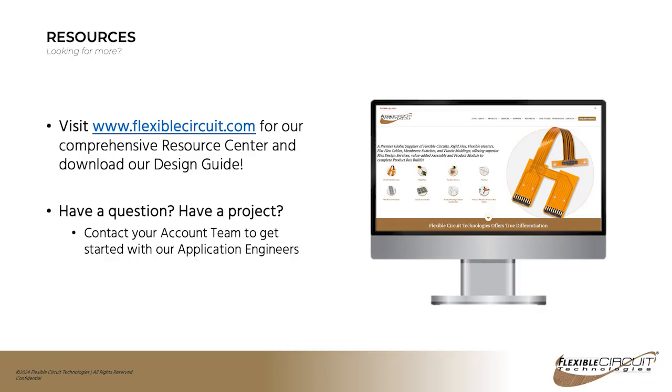Is there any consideration in using fine pitch or ultra fine pitch components on flex circuits? There wouldn't be any additional concerns other than just the fact that if your circuit is fairly large, those fine features are going to be more difficult for us to define than it would be for a rigid PCB manufacturer. So when you have a large circuit, it could affect the yields.